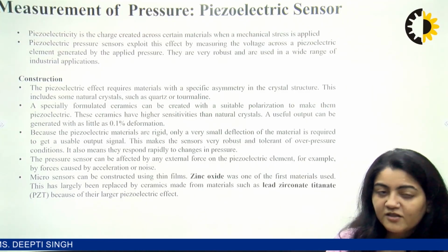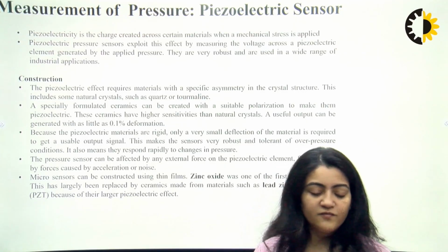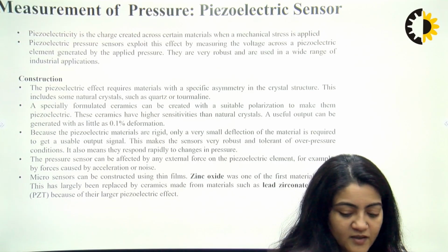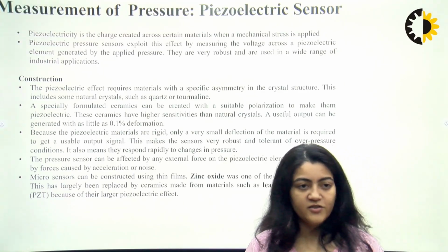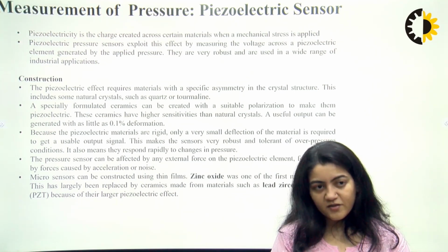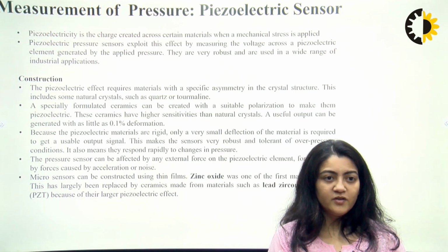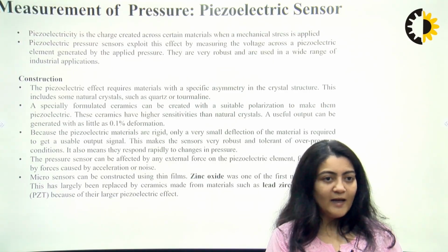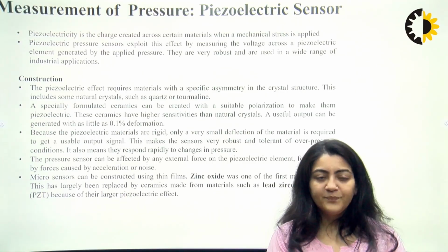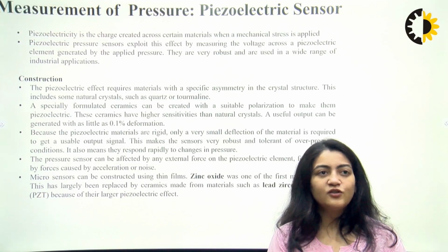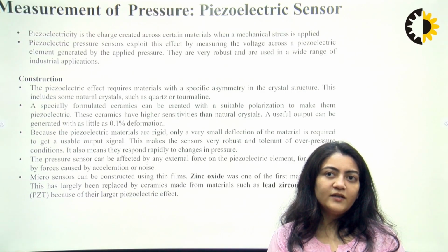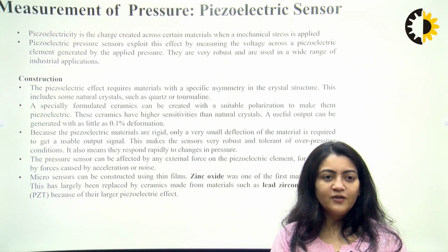And if we see what the applications are, when you go to the force sensor and when you go to the pressure sensor, this depends mainly on the applications. The strain gauge and the piezoelectric sensors are those which can be used in industry. But depending upon what you want, if you want higher sensitivity, then you especially go for the piezoelectric sensor rather than the strain gauge sensor. Then again, with piezoelectric sensors, the signal conditioning circuits are very much better as compared to the strain gauge transducer.